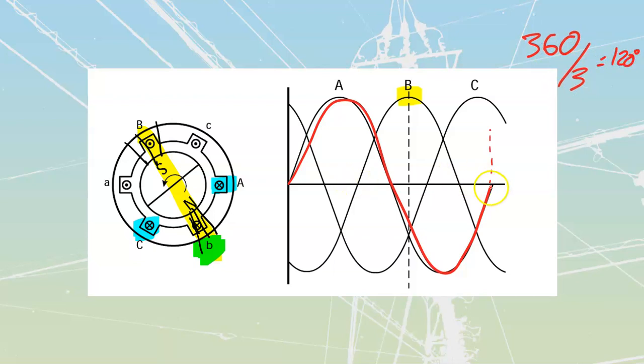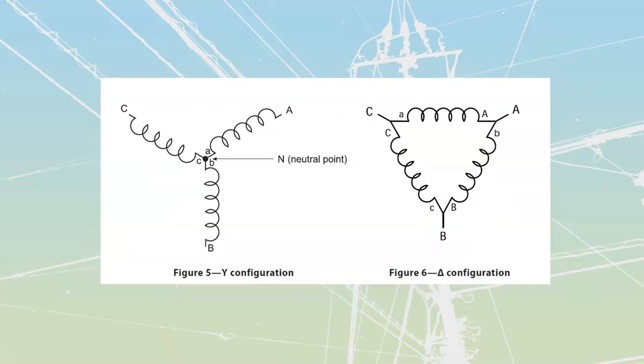And if I take a look at this length over here and I divide it into three different positions over here, I'm going to get one that's going to be right over here, and another one that is going to be right over here. These lengths, that's a third, that's a third, that's a third over there, are going to correspond with where I see each of my voltages themselves starting. Right over here, I see A starts over there, 120 degrees in, B starts 120 degrees in, C is going to start. They're 120 degrees positioned out of line from each other.